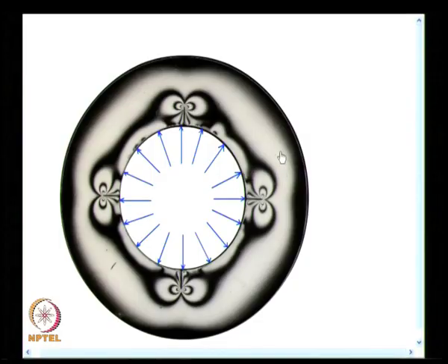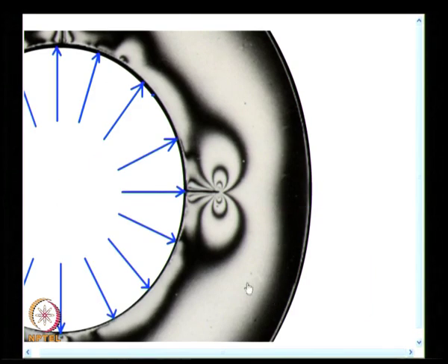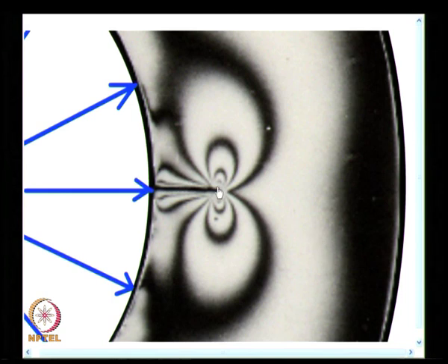Now, what I will do is I will magnify this further and I want you to observe a few more things. I think it is reasonably big enough. Let me see one more. And can you see here I have this as a crack. In the earlier examples we saw the fringes were tilted forward. Here the fringes are tilted backwards. You have a very complicated combination here. The first fringe is backward tilted, the second fringe is also backward tilted, the third fringe is forward tilted, and the inner fringe is almost straight. If your eye is tuned, you will be able to see this.